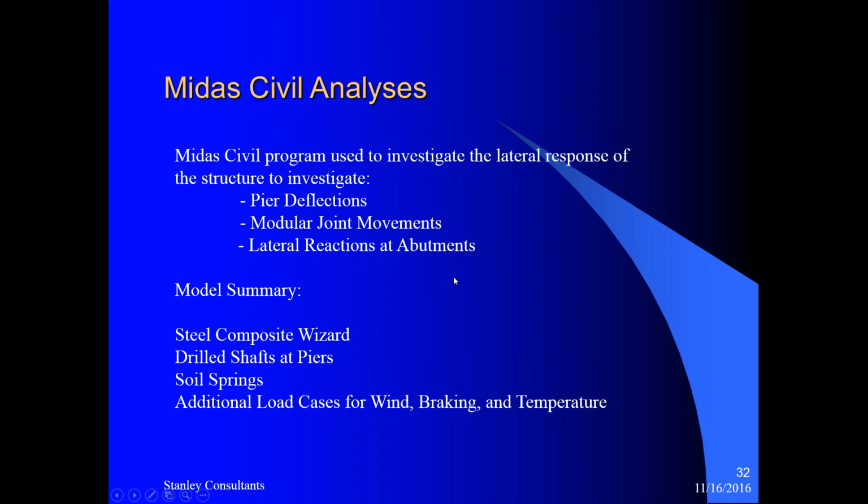The concern here is that since the piers are very flexible, but abutments are relatively rigid, the lateral forces will propagate towards the abutments and increase the lateral reactions at abutments, and perhaps the modular joint movements.